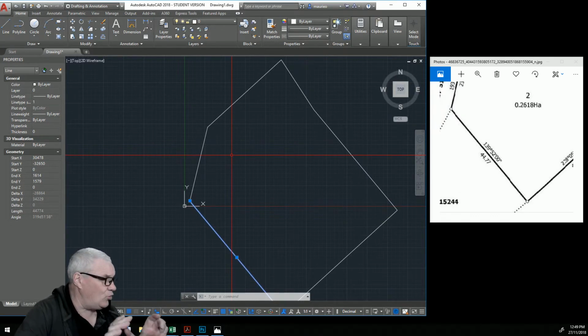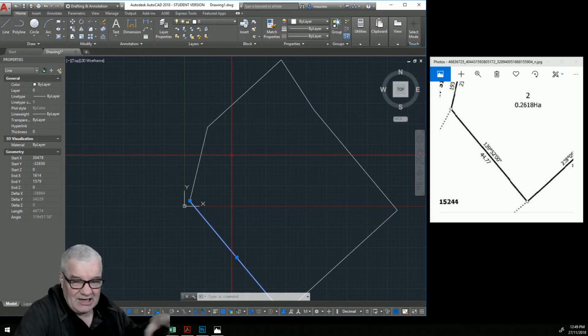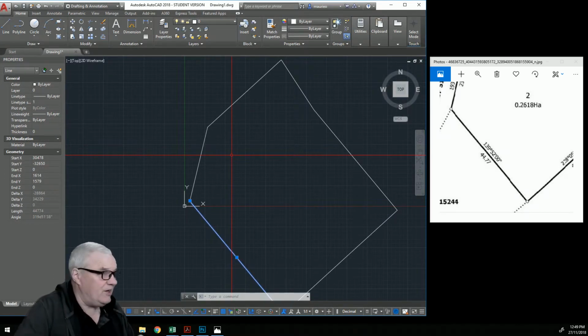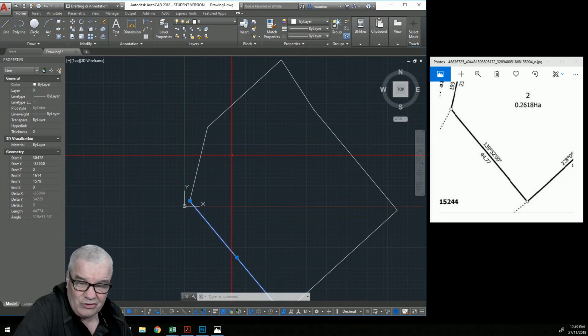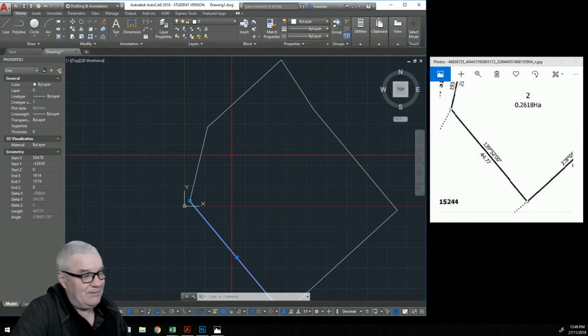When I'm drawing this up as a surveyor, I do a calculation and adjust the error out and put a little bit at each angle, at each boundary corner, but that's not always possible in AutoCAD, so just put all the error in that one little spot. But you have to remember that the error is there, because if you start doing dimensions off this model of the boundaries to buildings, you could put the error into the building, and you don't want to do that.